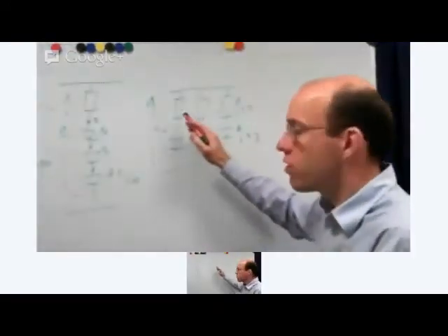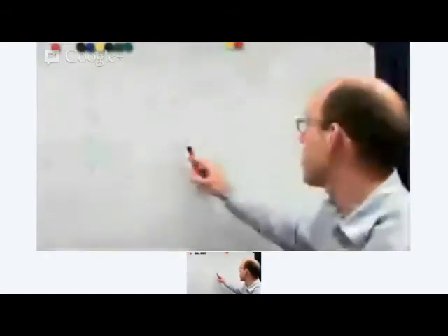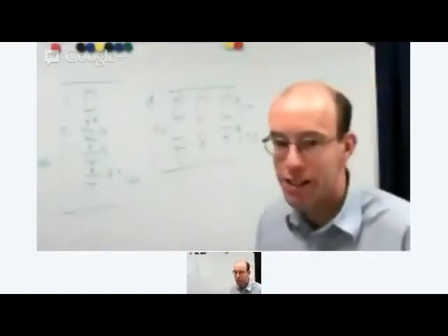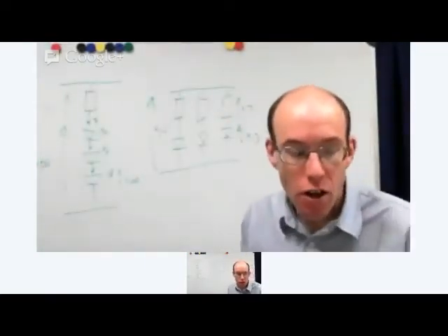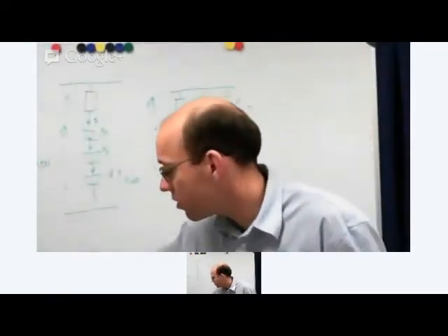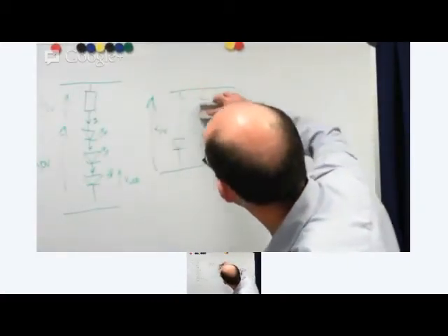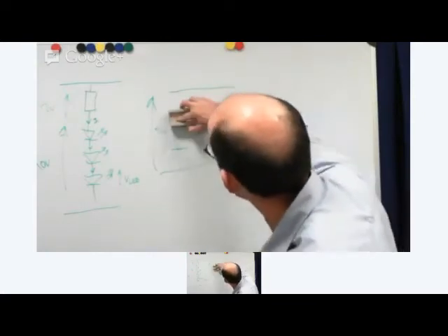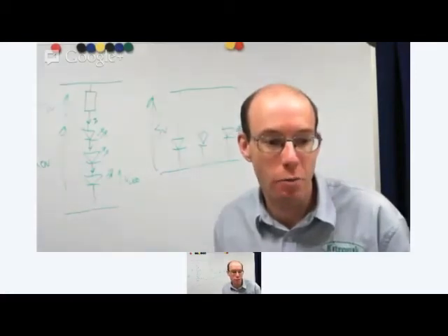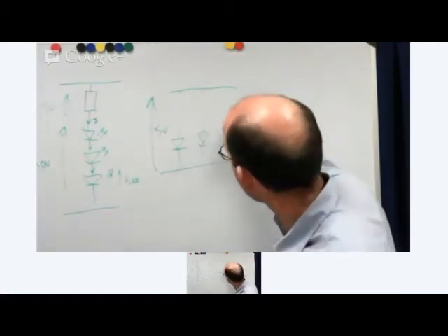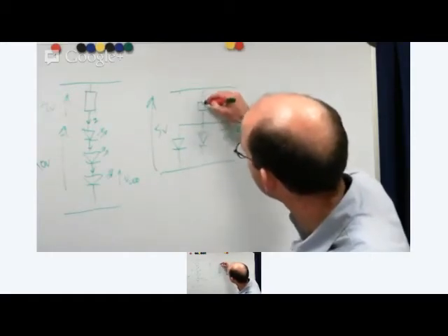Now the problem with this is that obviously we've got one current limit resistor for each LED. Now that will give you exactly the right brightness on each of those LEDs, but you do need a separate current limit resistor. So what a lot of people choose to do, and it does work fine, but it's not necessarily the best practice way of doing it, is this. It is perfectly good if all the LEDs you're doing are the same and they've come out of the same bag, so they've been made in the same batch. You can connect all those together and just put the one current limit resistor in.